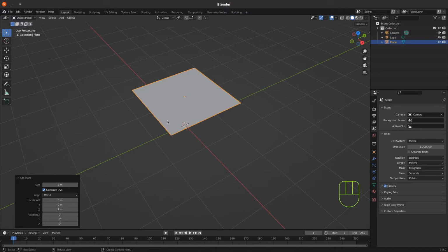I've got a different thing where I've got 3 meters of 50 by 75mm box section, which I'm going to use with the 50mm as the horizontal width and 75mm as the vertical height of the box section when it's in place. And if I cut one in half to 500, it gives me a tabletop size of 1 meter by 600 out of those 3 sections if I cut one of the lengths in half. So we've got to now make the plane 1